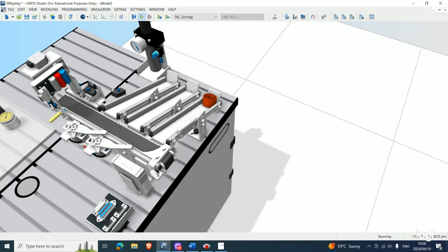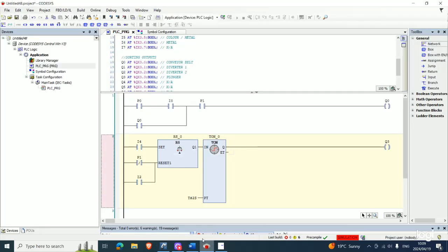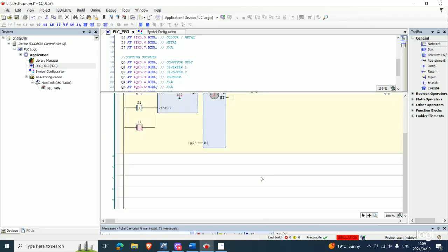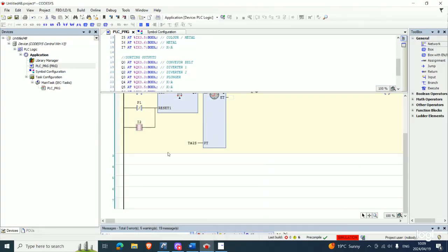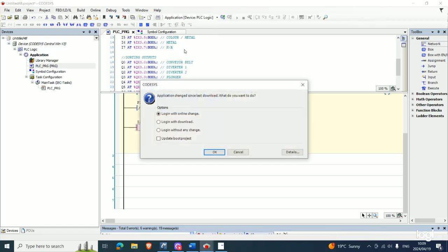It only becomes on when it detects a workpiece sliding down, right? So now you can conclude that we don't have to negate it because it's only going to get activated when the part slides down one of the slides, and then that's when it's going to reset our timer, right? So yeah, that's the situation. So now, let's run this.